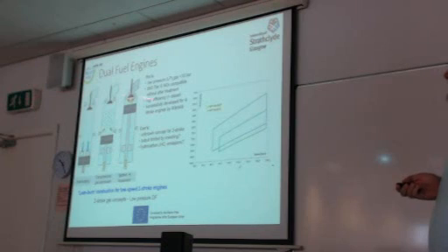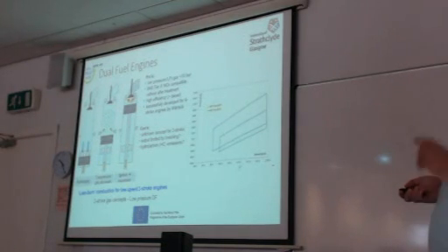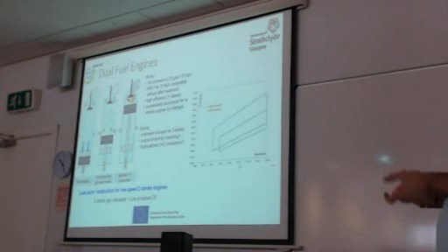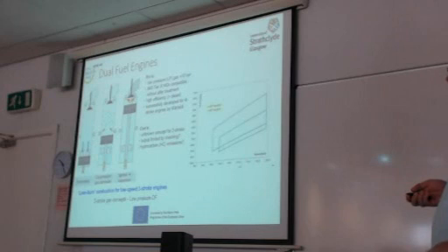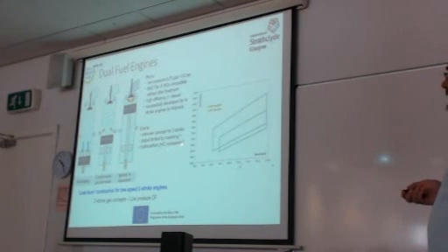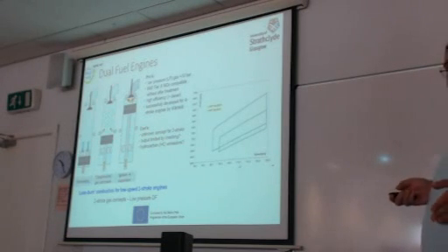Of course, the advantages of the concept are low NOx, low SOx as far as natural gas does not contain sulfur at all, high efficiency, and low pressure of the natural gas. The natural gas is injected at a pressure of 5 to 7 bars, so I think the pressure of the natural gas piping system should be around 8 or 10 or 12 bars, something at this level. We keep this value because we need to discuss it in the case of the other concept, the direct gas injection used by MAN Diesel and Turbo.